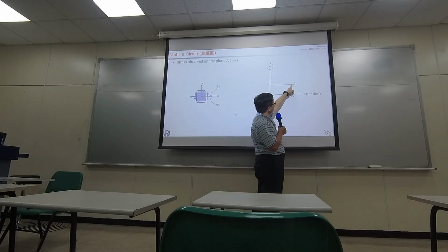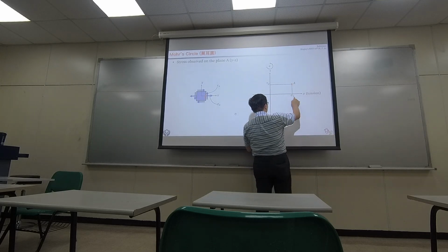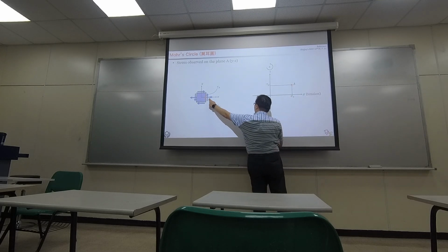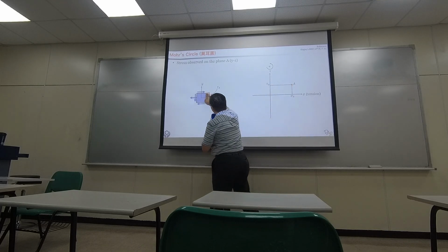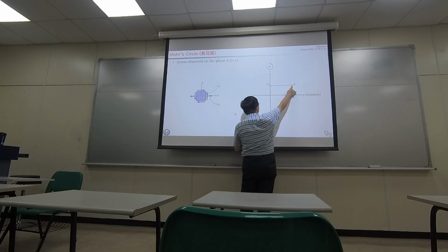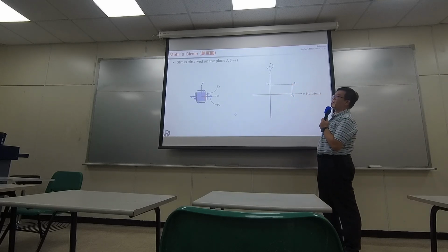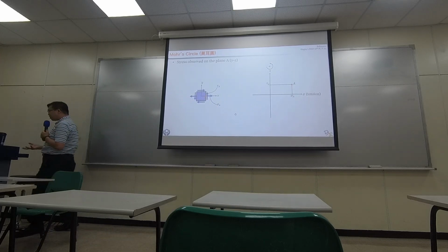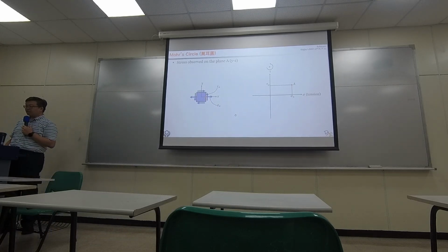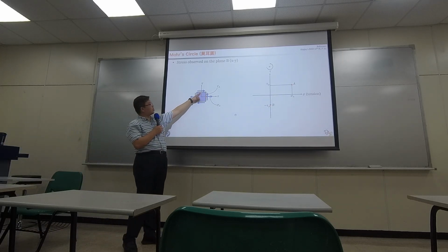Then you should have a point right here. This is the amount of normal stress at point A, and this is the amount of shearing stress at point A. So this is the load condition at position A. Now the investigation at the first point is done. You can start to change your position, and move to a different place like here.